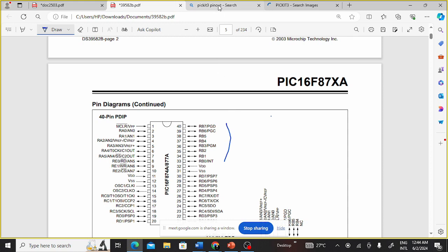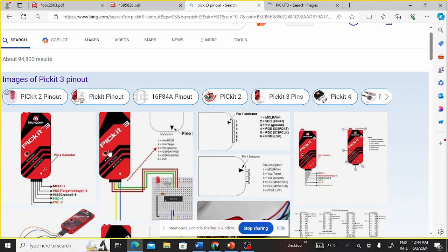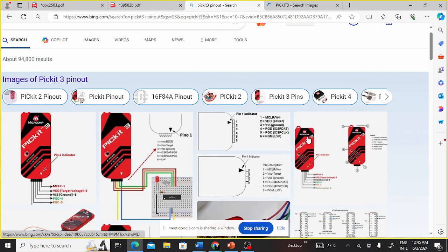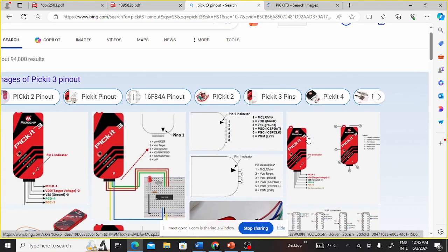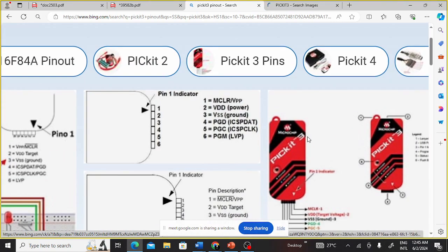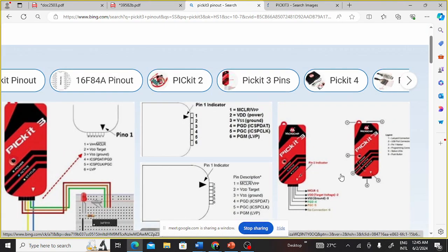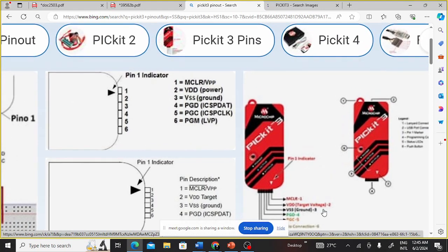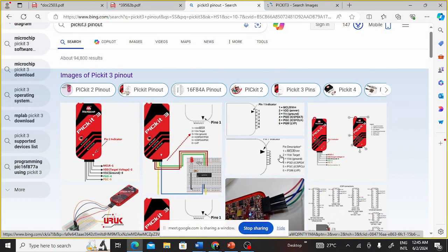Yesterday I was explaining something about PIC, program on the go. I think I talked about something like that. There's something that is possible with the PIC programmer, that you don't need to keep going back to your software. When I was explaining on MPLAB, if you put your program in that mode, you just keep pressing this button, connect the new microcontroller, press this button, connect the new microcontroller, press this button, and it will just be flashing the same code.